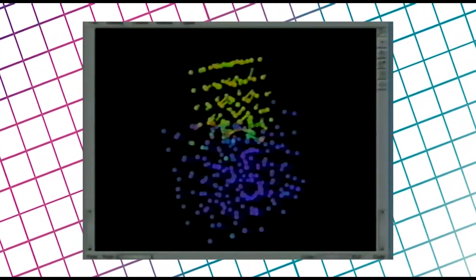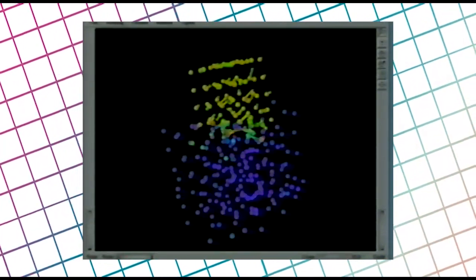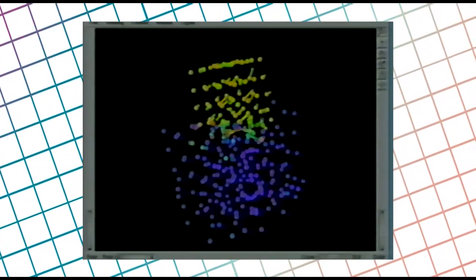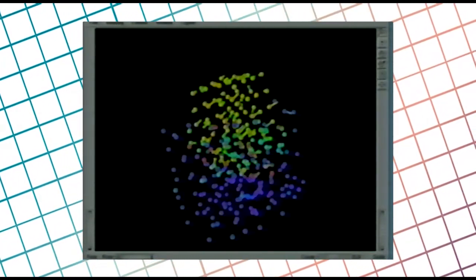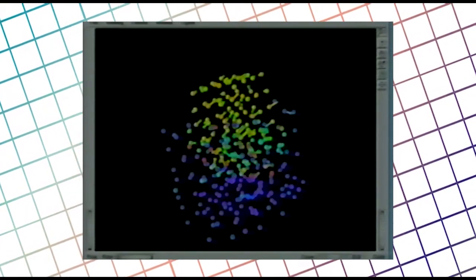Simulations of these collisions help us understand the complex interactions that may occur between individual atoms, including stress tensors, potential energy changes, and heating. With GlyphMaker, we can see many of these attributes at once and quickly find unusual correlations. By isolating the impact region and then removing the sodium chloride crystal, we see that the area of high temperature in the neon is localized only below the impact region, a result that is obscured before we remove the sodium chloride crystal. Here we see tensor data bound to vectors and temperature values bound to color, so we can see the relation between force distribution and heating.